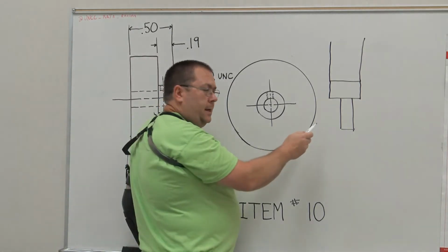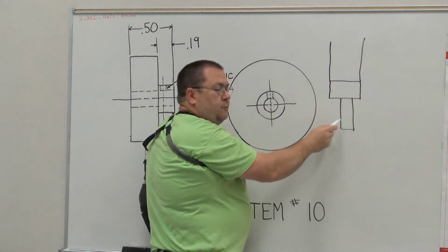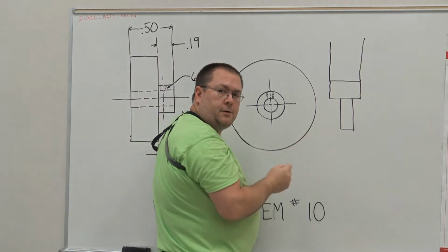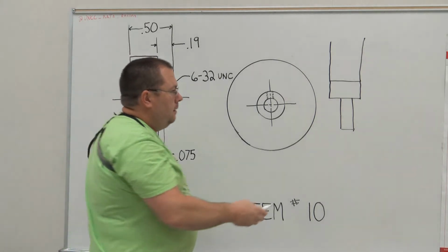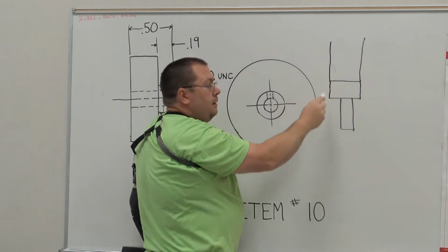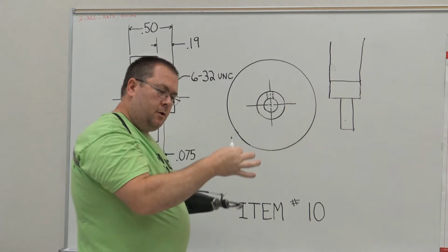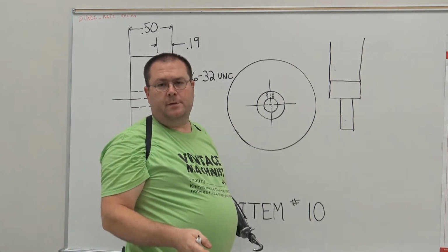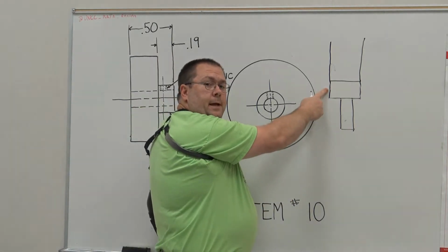We know already, because we've used it before, that this major diameter of what I'll call the business end of that edge finder is 200 thousandths in diameter. The shank, which you hold in the drill chuck, and the larger body that is also a component of that 200 thousandths diameter, on all of the edge finders that you would buy for the machine shop that we specify, that diameter is going to be 3/8 of an inch.